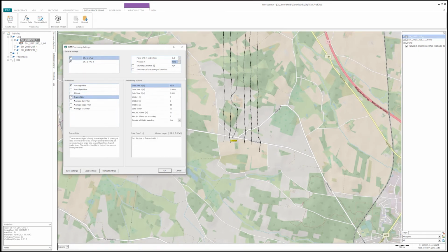And then we come to the trapeze filter that creates the average data by going through the width of each trapeze, and you set which time should apply to each width. Within each width, we also have the spike filter that you can set. If it's set to 20, it means it takes 10% of the top spikes and 10% of the lowest values for spikes and removes them.